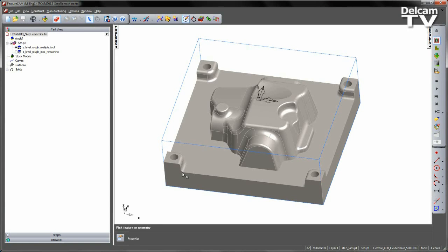FeatureCAM 2013 has a new method of remachining, which minimises terracing when creating Z-level roughing toolpaths with large step-downs. Rest machining of the terraces remaining from a large area clearance is done with the same tool in the same toolpath. This method also increases the feed rate of the intermediate slices as the depth of cut gets progressively smaller, enabling a constant volume removal rate.